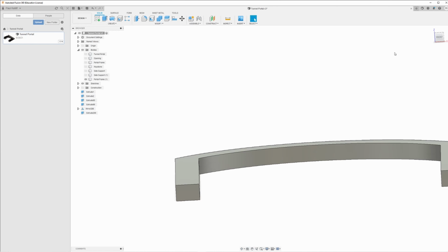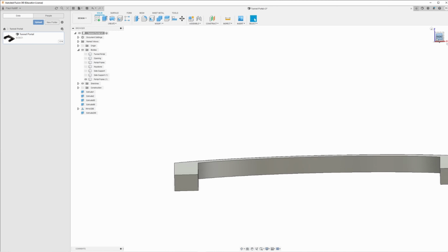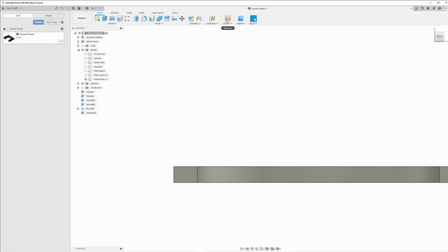I'm actually going to take a real quick measurement of our thickness to see how much I want to thin it out. So we're going to grab our little ruler up here. Let's go from that corner just to this corner. And it's 0.44 of a centimeter, which is almost 4.5 millimeters. I think this only needs to be, let's knock it down to 1 millimeter thick, because once we add on the brick texture, it gives us enough thickness.